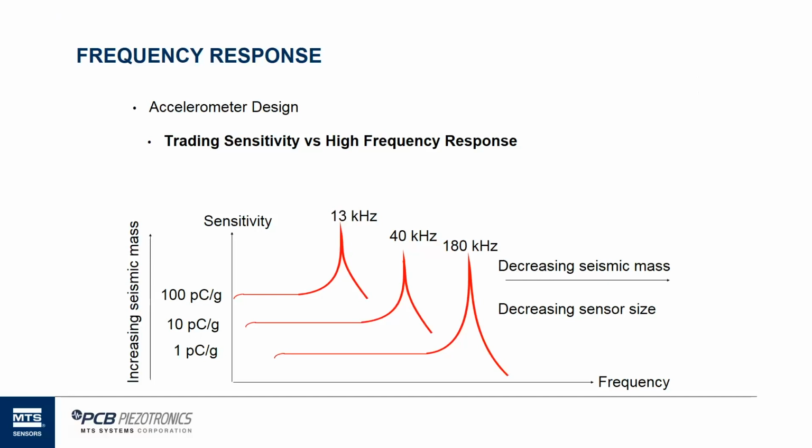And on the bridge, you can tolerate that high mass accelerometer, so it doesn't affect the vibration of the bridge, but also the vibration of the bridge is going to be very low level, so we need the high sensitivity of the accelerometer to draw that signal out of the mechanical motion. The takeaway is basically we have to trade sensitivity versus high frequency response. The other bullet we could put on here is that we trade mass for high frequency response. So if we want high sensitivity, we also have to tolerate higher mass.